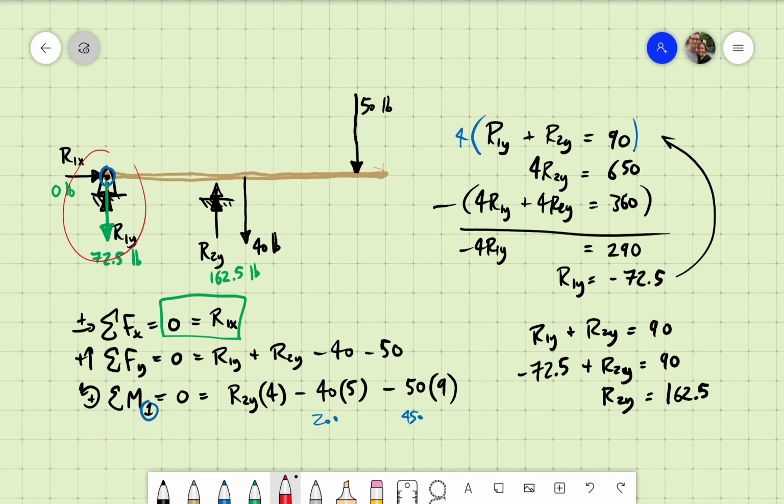So that's really straining. What this tells you, and we're going to do this later in the year, is that this board could actually break around that spot right there, where that peak force of 162.5 pounds is. Or at least it tells you that if it is going to break anyway, it's going to be right there. And this just shows you the power of moments, which is actually a book on my shelf, The Power of Moments. But the power of moments is that someone with a small force can magnify their force to create much larger forces, apparently for free, just by shifting positions.